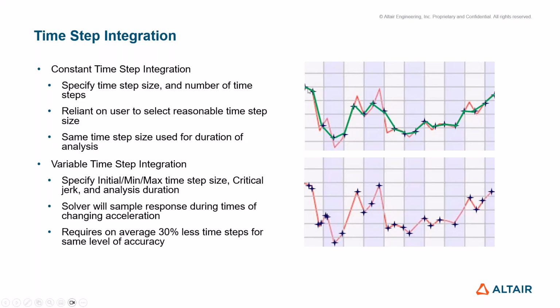And here's an example where let's just assume that we had 0.01 second increments between each one of these y-axis grid lines. And if we selected a time step size of 0.005, so basically we land at each grid line and halfway in between, we can interpolate those points, and you can see here that the green line is looking a little bit different than the red line, which would represent the true response of our structure to this loading.